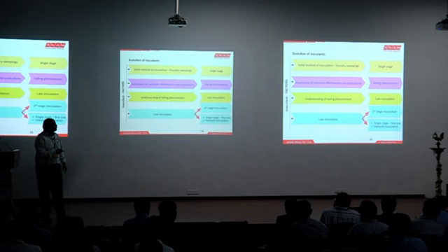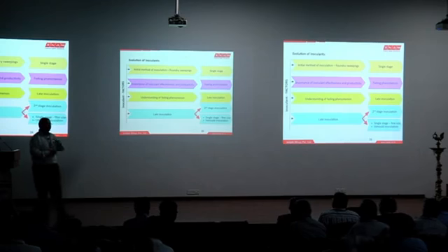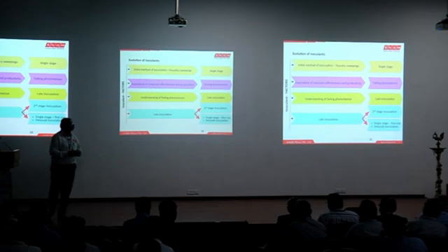Initially it would have been a single stage, and when the importance of inoculation effectiveness came into the picture, the fading phenomenon was understood when you started to pour greater than 4 minutes, greater than 6 minutes, greater than 8 minutes. Then the fading tendency, or variation in the properties with respect to time of filling or pouring, came up. Once you understand the fading phenomenon, you wanted to get the same properties at the last box pouring also. So we tried to either split the inoculant or do a separate inoculation at the end.